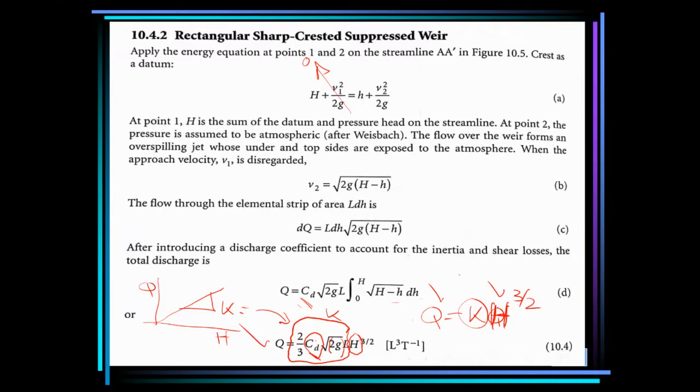Okay, it varies. And what is the physical meaning, the interpretation of the value of CD if you go to the lab and determine it? This is one of the questions that we probably ask in the lab: whatever you find, what is the meaning? Okay, let's go. You go to the lab, do the experiment, which we are going to do this afternoon. Determine the coefficient of discharge, CD, which will be equal to, let's say, 0.61.